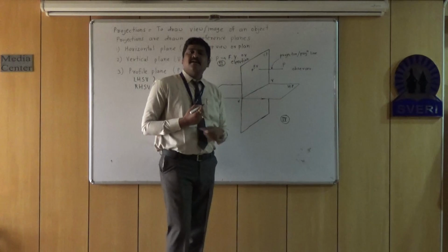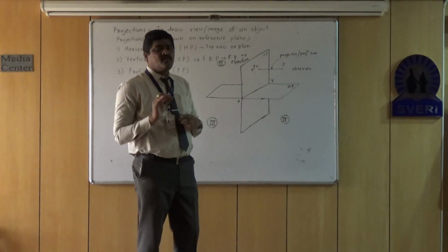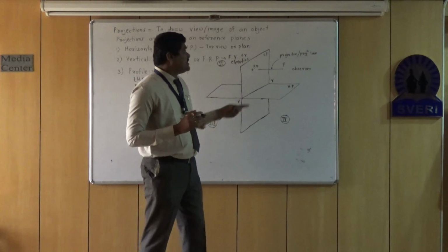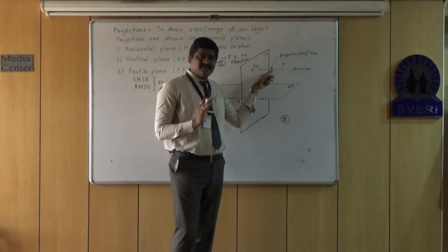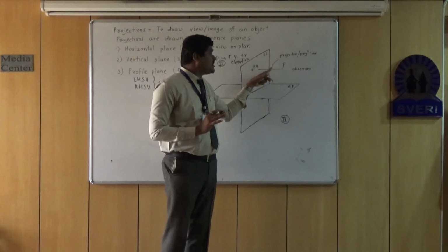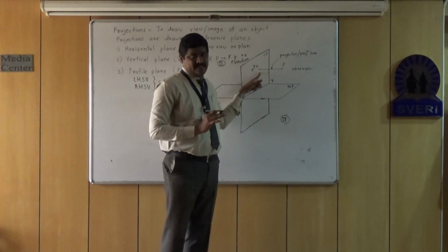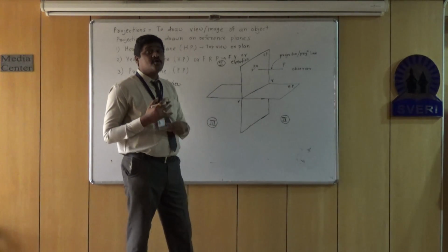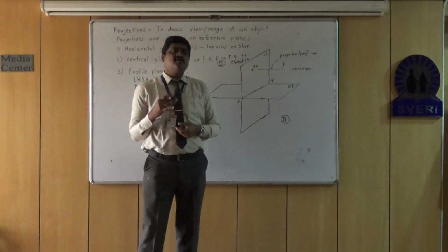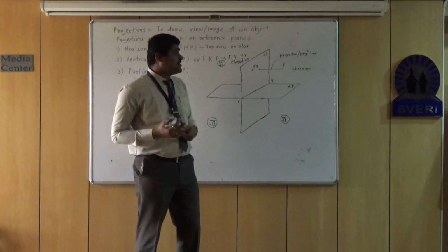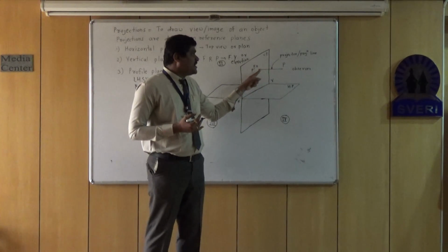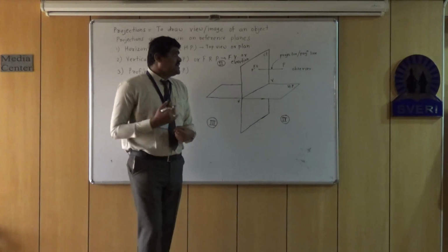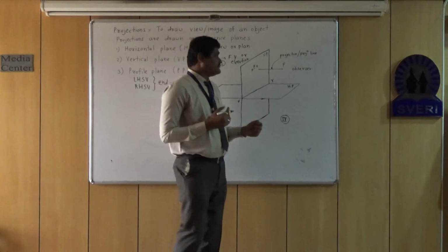It is important to note that whatever method of projection we are using, the projector or projection line is perpendicular to the reference plane. Hence, this type of method is also called orthographic projection. Ortho means perpendicular, in which the projectors are perpendicular to the reference plane. Then this is about the front view.